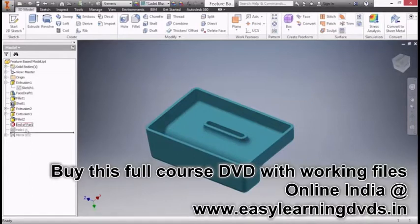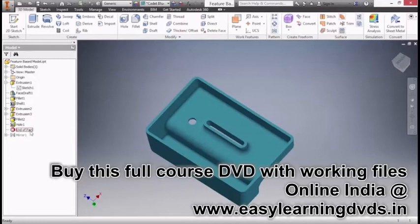And then we have hole 1. And then a mirror operation to mirror that across our origin plane. If I expand the plus sign there and the features underneath that, you can see how that took that hole and included it in that mirror. I'm going to collapse these items.